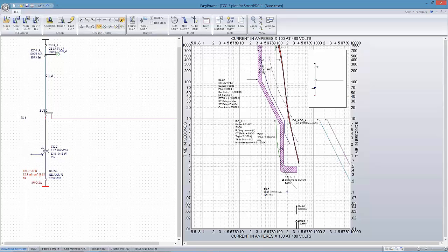So at the very least, there needs to be some adjustments here, and offhand I would say, you see as I move the relay curve, and I got it kind of out of whack here. As I move the curve, you can see it changes the incident energy being calculated for that bus. Look at the incident energy here as I change the settings on the curve. Okay, so that's an indication of miscoordination.